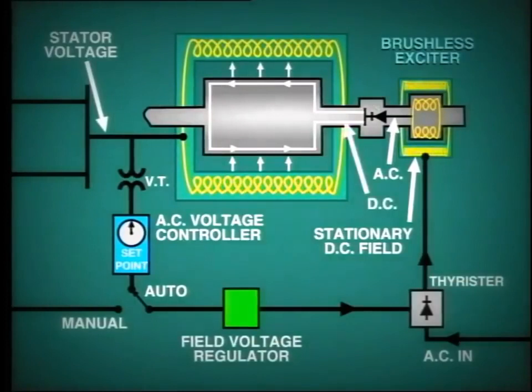The DC output from the rectifier is connected directly to the main rotor winding through leads which pass inside the shaft. There is no need for collector rings or brushes. Control of the DC excitation current is effected by adjusting the strength of the exciter magnetic field, and this is done by controlling the DC current flow through the field winding. This DC field current is supplied from a rectifier which is located in a nearby cabinet.